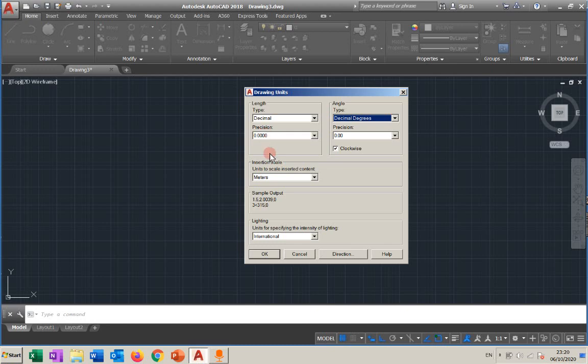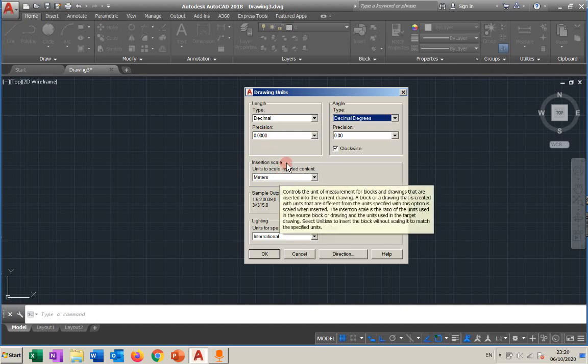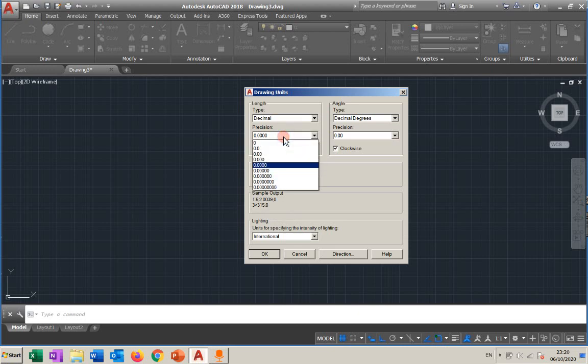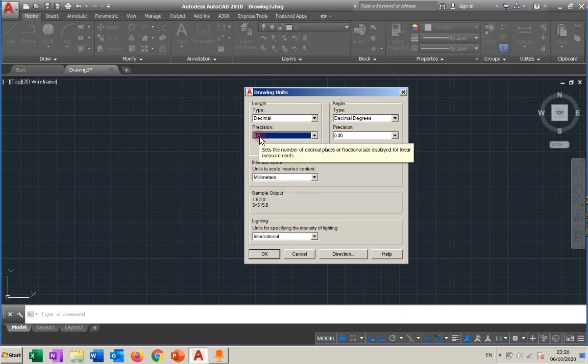Now the precision, it depends on the units that you have. Let's say that if you're in millimeter, four decimals are not required. Precision of 3 will be enough, it's more than enough. Even for millimeter, one precision is enough. After the decimal, 1 digit is enough. Why? Because it's millimeter. A tenth of a millimeter is enough. No need to go for the 3 or the 2.